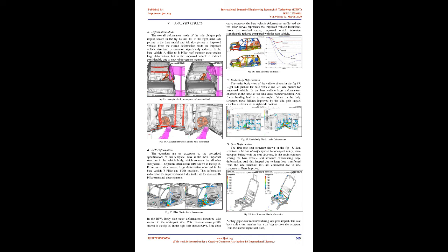Both components are partly manufactured from ultra-high strength, hot-formed steel. The impact forces are transferred from the B-pillar to the opposite side of the vehicle first and foremost via the transversely rigid seat and the center console. A further load dissipation path runs from the base of the B-pillar to the cross-member under the seat and transmission tunnel braces.